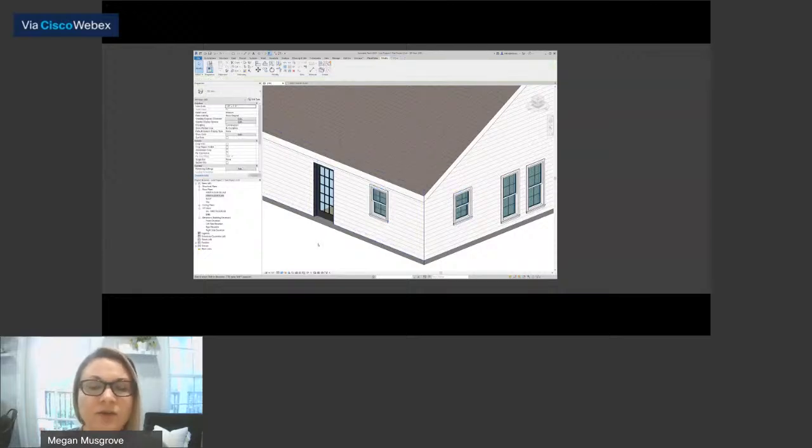Our standard height for kitchen counters is 3 feet. So as long as those windows are over that, I don't like to have a huge gap. I like those windows to come down pretty low. Depending on what you're doing, sometimes you might want them to come down where they're actually flush and you can have your counter go in there. You need to be controlling your water spillage if you do that.